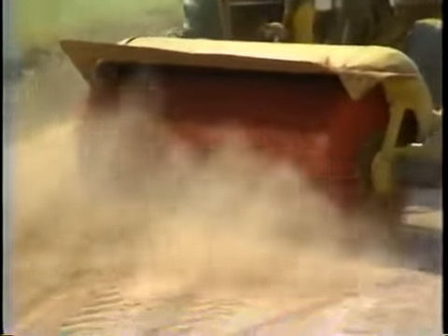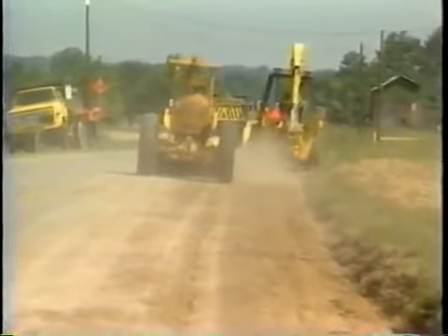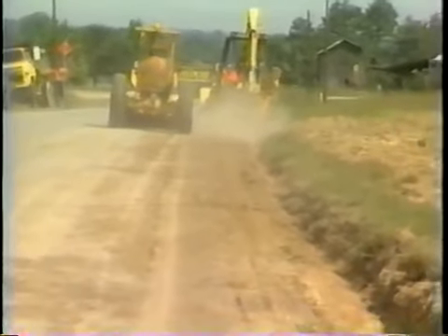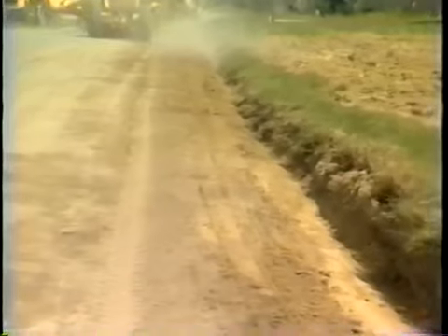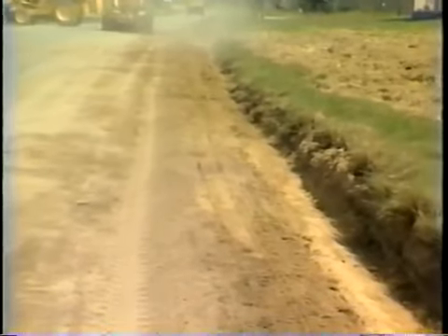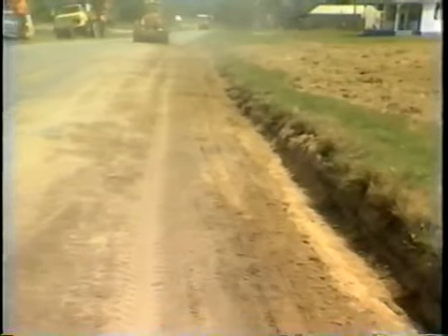If necessary, broom excess material off the pavement with a power broom. The repaired shoulder is flush with the edge of pavement. No buildup remains. Place seed and mulch as needed to reestablish vegetation on the unpaved shoulder.